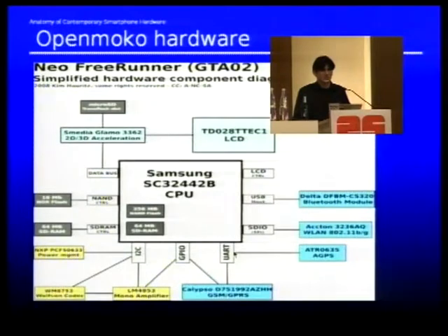But it makes me extremely worried if the GPS is connected to the baseband side. And then I should trust the device, it's like, the GPS data first goes into the GSM modem where all the deep secret GSM stack is running. And then the GSM data is forwarded to your application processor. So if you switch it off on the application processor side, is it really switched off, or does it still feed the location into the GSM modem?